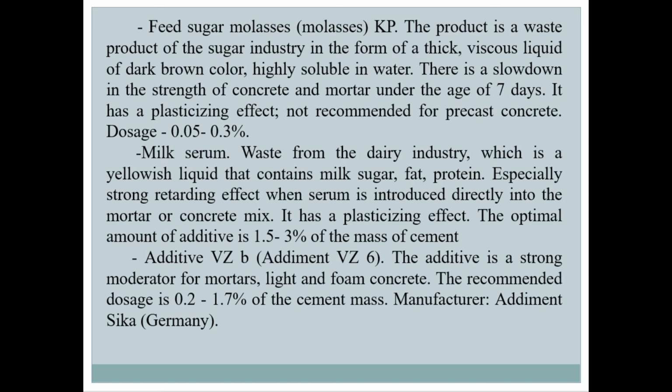The optimal amount of additive is 1.5 to 3% of the mass of cement. Additive VZB, Adamant VZ6. The additive is a strong retarder for mortars, light and foam concrete. The recommended dosage is 0.2 to 1.7% of the cement mass.